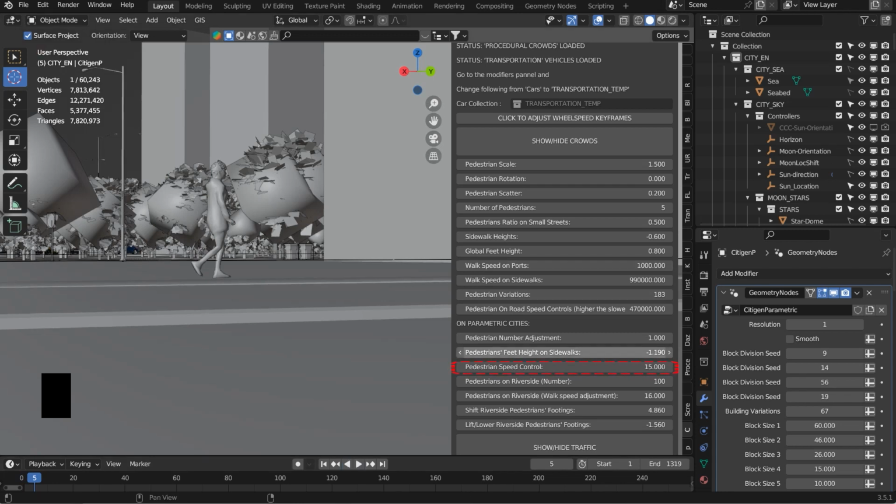She's fleeting fast, so that means 15 is too fast. Let's lower that to 7 and see how she walks. That's 7. Still she's fleeting forward. That means that's still fast. Let's change it down to 3 and see if her toe stays where it's supposed to be.